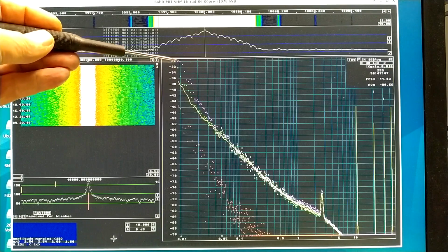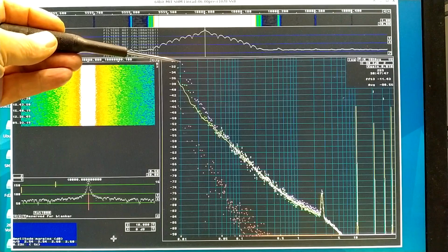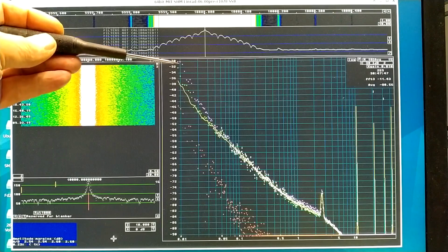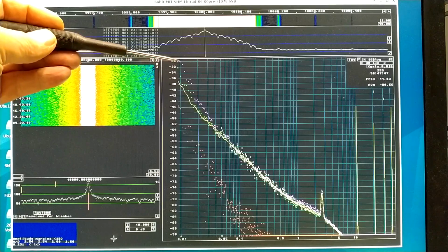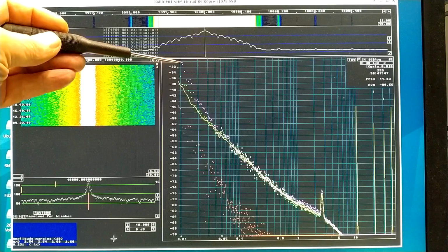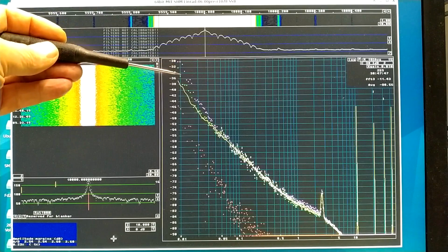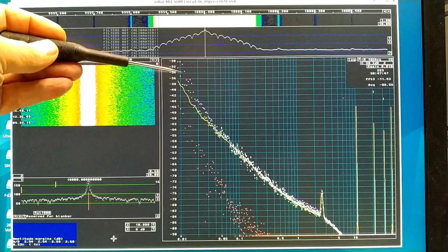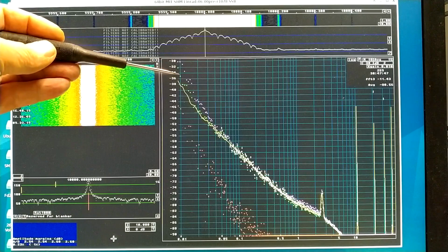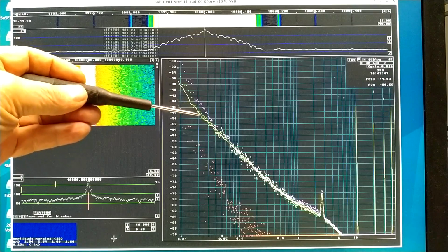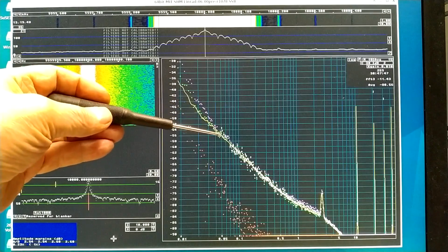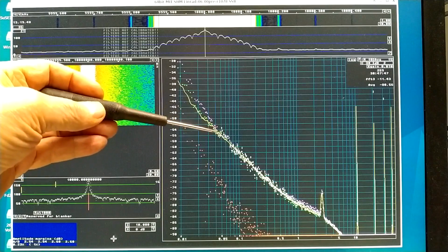There is a disadvantage in that the noise is about 5 decibels higher in channel 2. It could be better to make the time constant a little bit faster, but making it too fast means that I would have the noise of the rubidium oscillator. So I don't know for sure, but anyway, I can measure easily down to 0.05 hertz with good precision,